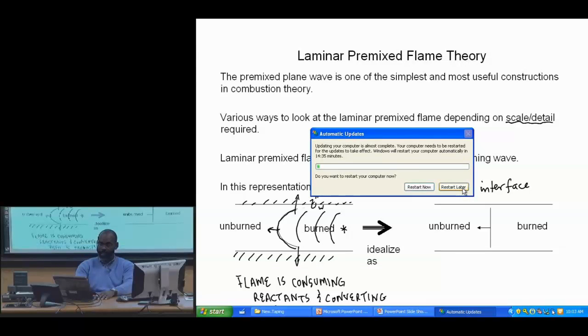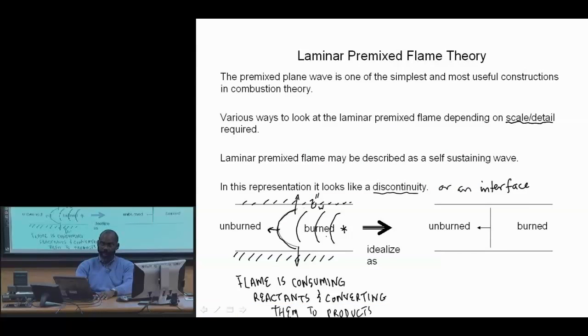So you have a cold wall, and that cold wall is causing something called flame quenching. And so that flame quenching is inhibiting the propagation rate of the flame, and so you can imagine that that would cause this relative slowdown in the flame propagation process, in the flame speed. But it's more complicated than that, and there are more likely stability questions and issues that drive it.